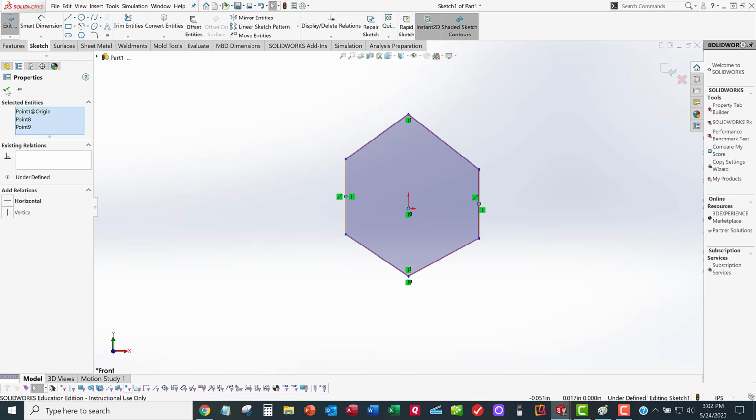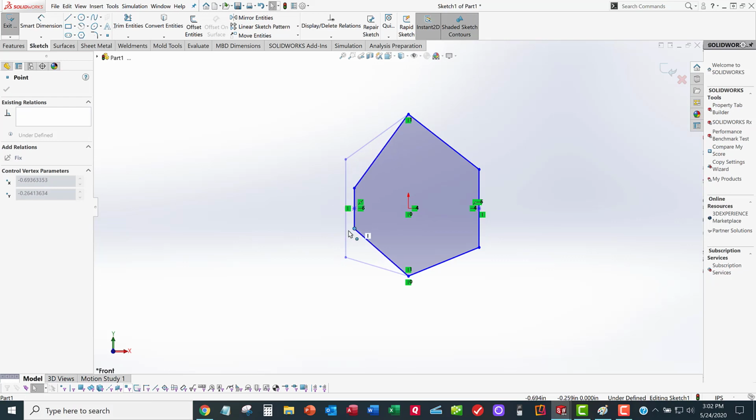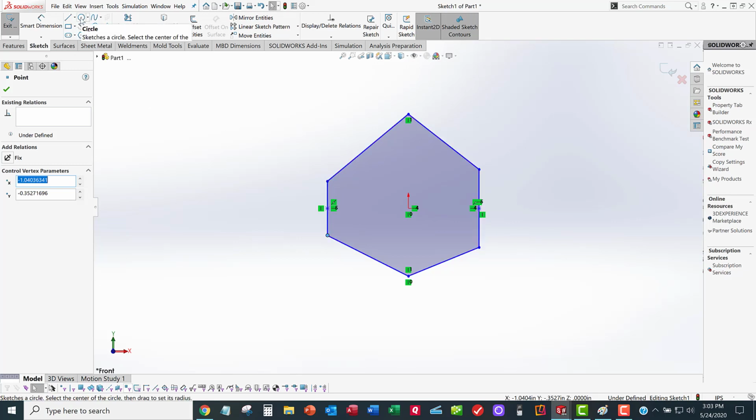Now what do I want to do? Well, I need to find some blue corners and drag them around and see what makes sense. Well, a couple of things come to mind. These lines here should be parallel to one another, and these should be equal as well. And so I can do combinations of parallel lines, equal lines, but I'm going to think of something else, and I'm going to make me some construction geometry. And so let me do this, and I think once I do it, it'll make sense.